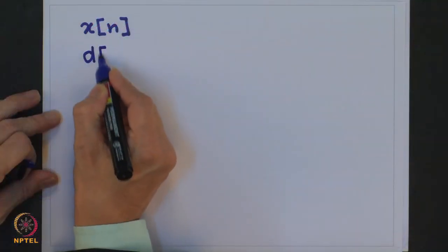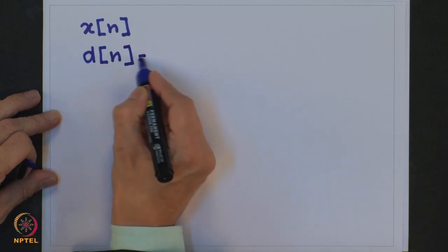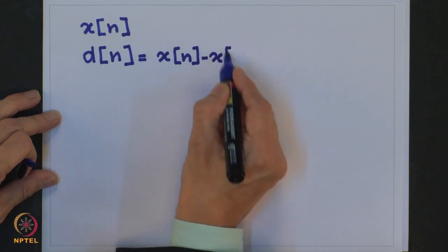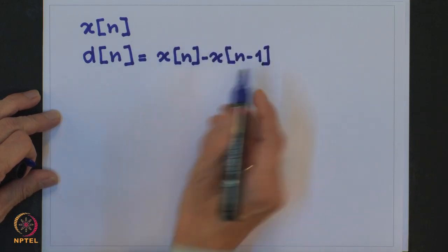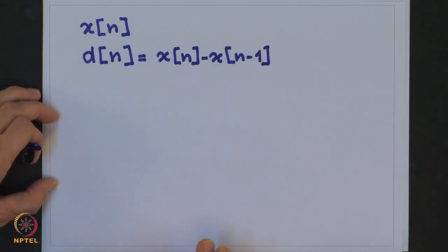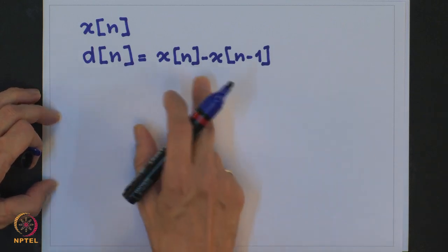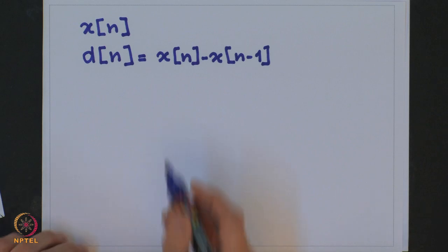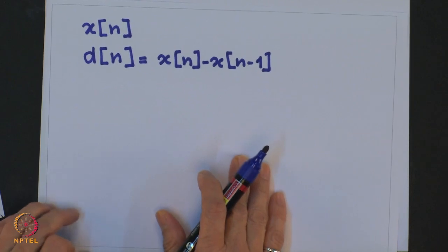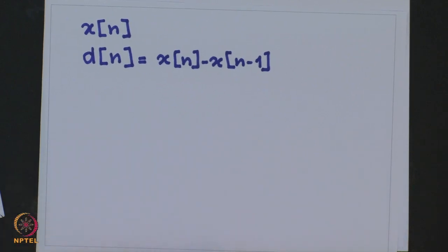What this means is that both the dynamic range and the variance of the sequence of the differences, defined as follows, are significantly smaller than that of the source output sequence itself. Furthermore, for correlated sources, the distribution of these differences, that is D, is highly peaked at 0.